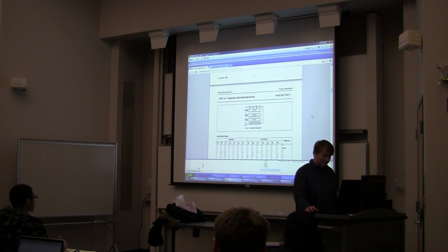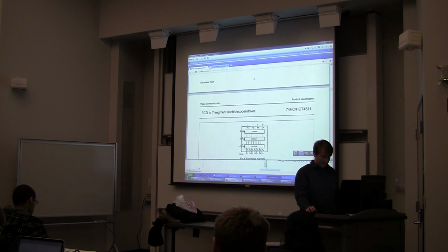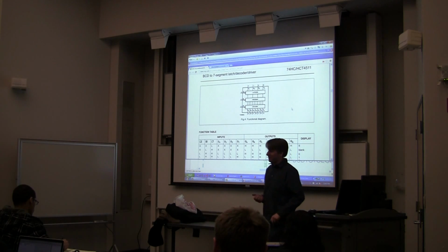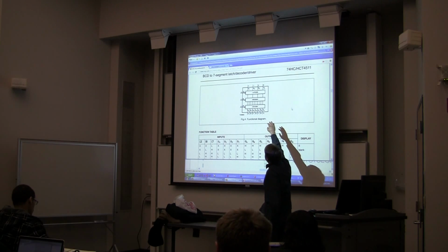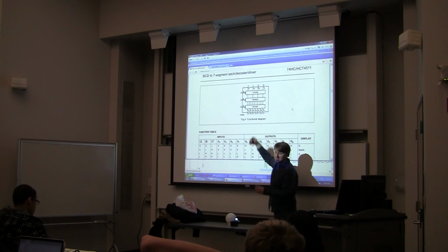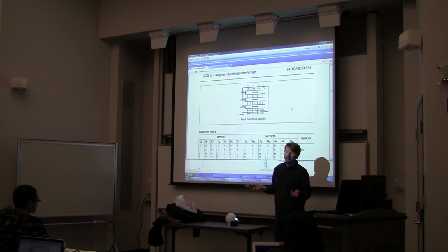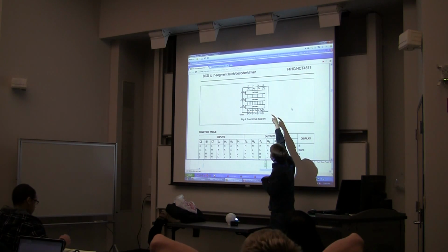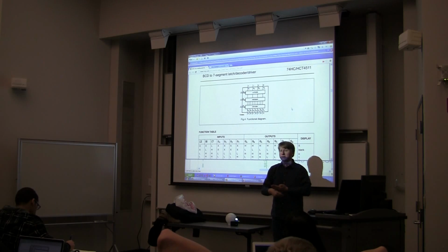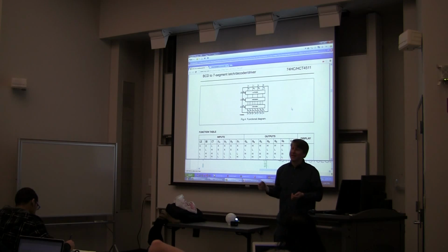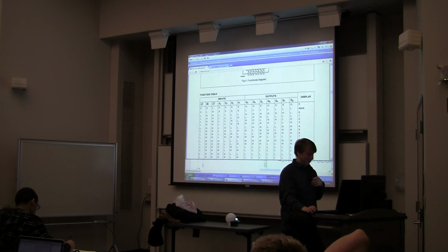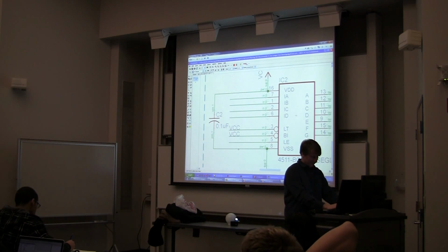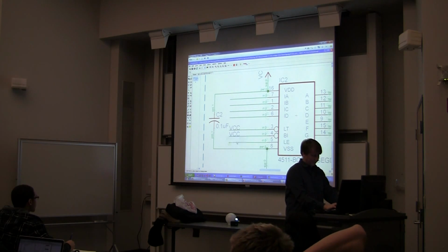So for those of you who are interested, if you were back in the 80s trying to make a product using these and you wanted it to always be nice and work well, you basically have the decoder of the drivers. So whatever the decoder sees, it's going to display that digit. And so the latch allows you to sort of load the next value before you're ready to display it. And then when you toggle the latch, it will do something. But I don't think I really care about that, so I'm just going to leave the latch low. So latch enable low. So name ground.